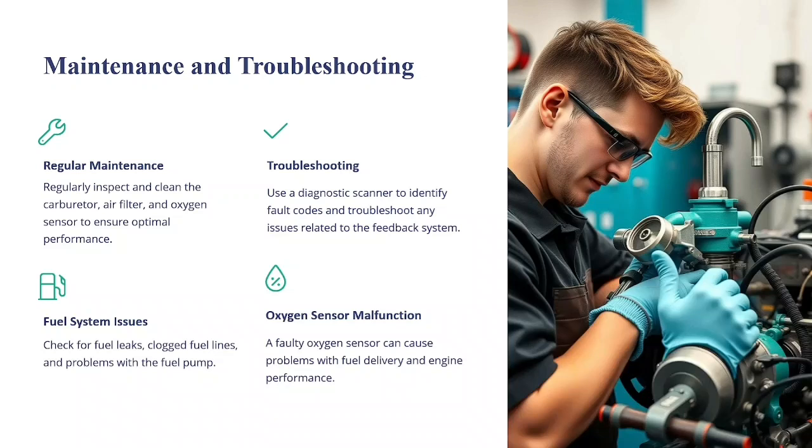To talk about troubleshooting, identify symptoms, that is poor engine performance, rough idling, decreased fuel efficiency. Then isolate the problems related to the fuel system, ignition system, or oxygen sensor, etc. Then fuel system issues: check for fuel leakages, fuel lines, and problems with the fuel pumps.